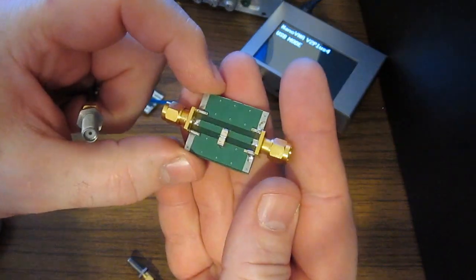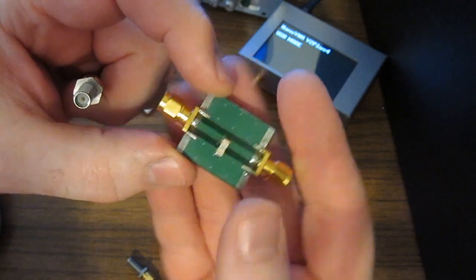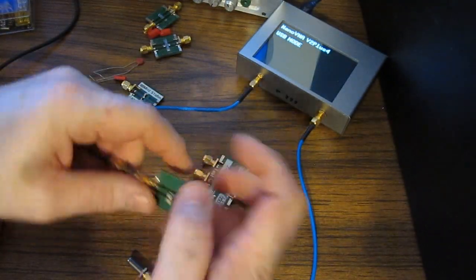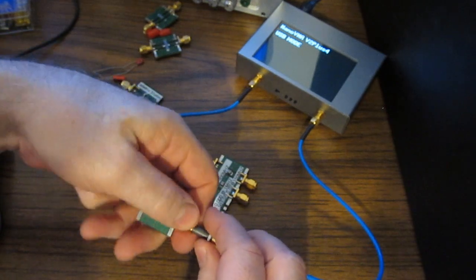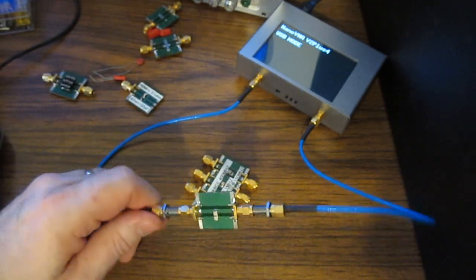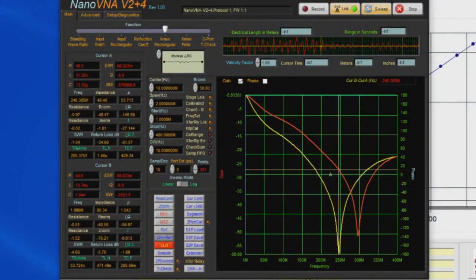So one thing we could do is place 2 of these capacitors in series, and we're expecting that ESR to double. Again, 2 resistors in series, so I'm expecting this is going to read somewhere around 63 or so milliohms. And you can see, sure enough, we're reading 67 milliohms. You can see it's also changed our resonant point.